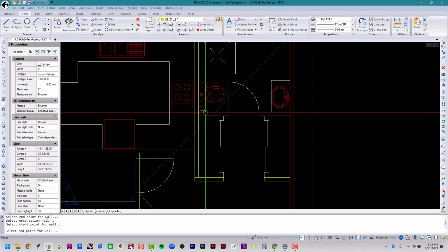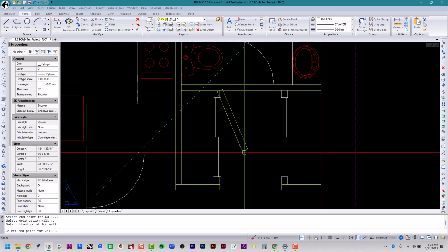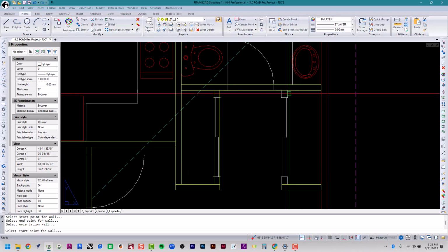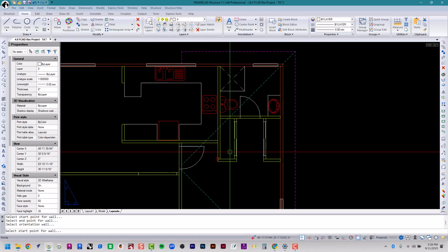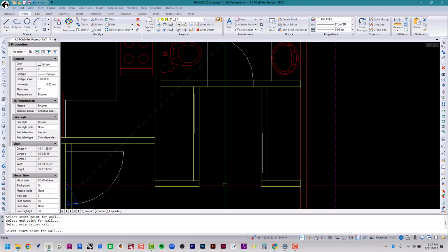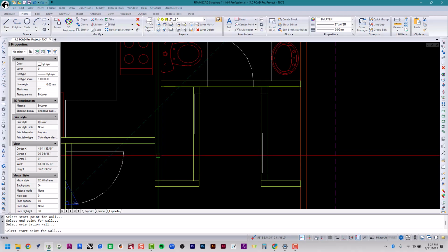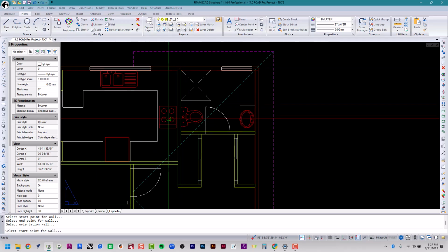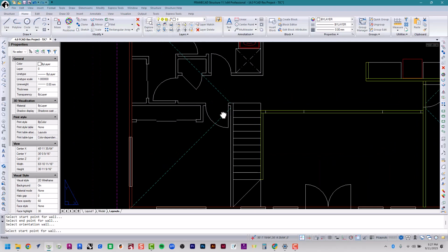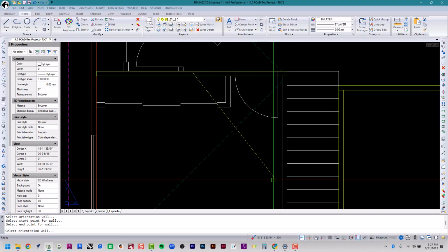This is a great exercise because as you're doing this, you're really determining how all these different panels are going to be manufactured, but also laid out in the field. You're dictating all that right now before you even get to the site. So you want to make sure there's some consistency, so that my framers don't accidentally have this wall come all the way down to here, and then this one goes out to the right, and everything's a little bit off, and then there's a gap over here on the left. You want to make sure you're consistent. So that's as consistent as you can be, within reason.